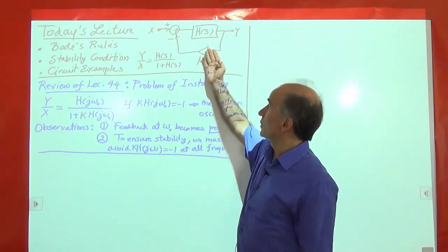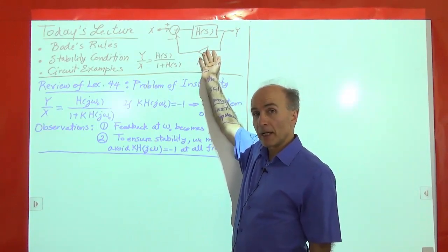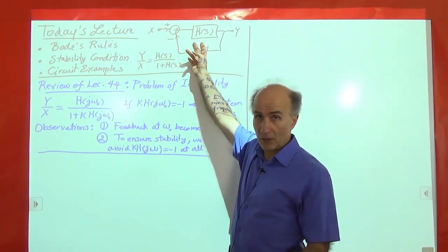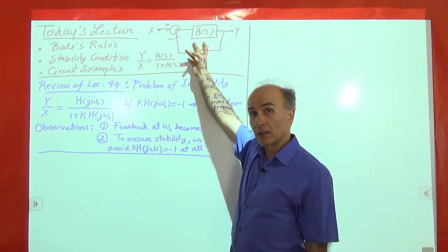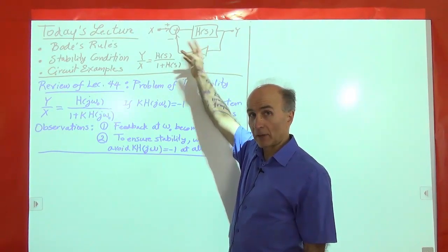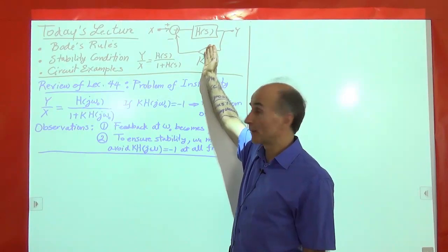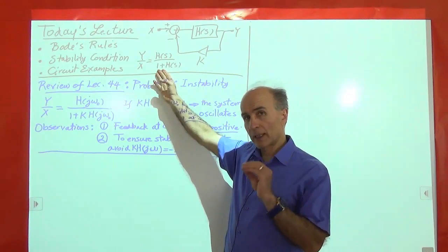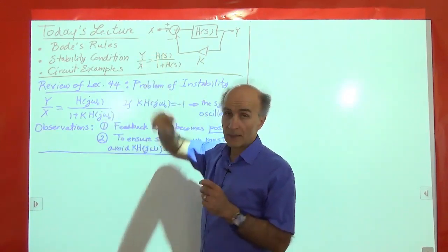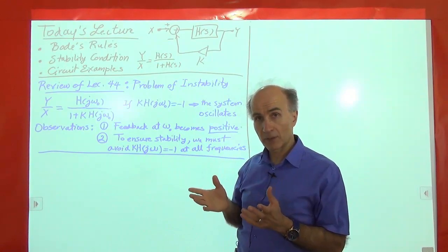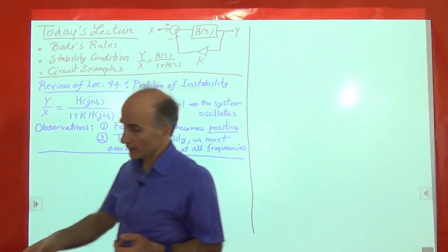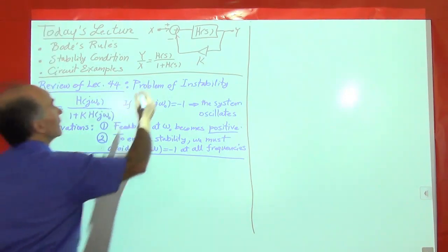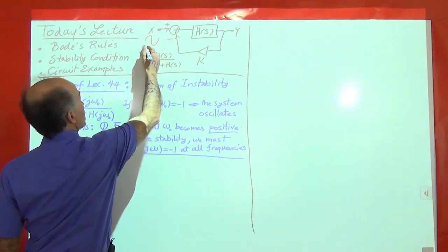We looked at this generic negative feedback system and we said, let's suppose that the feed-forward amplifier has some poles and zeros, so it has a transfer function, so we call it H of S. And the closed loop transfer function of the system is now given by this expression. And then I considered a special case where the input is a simple sinusoid coming in at the frequency of omega 0.